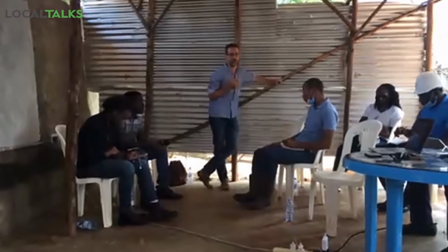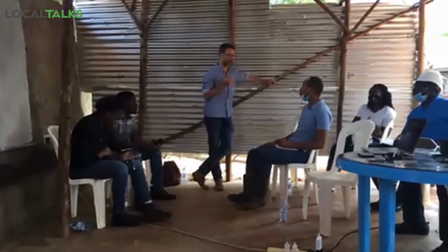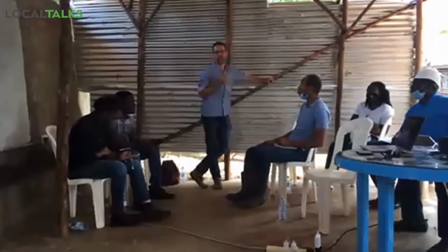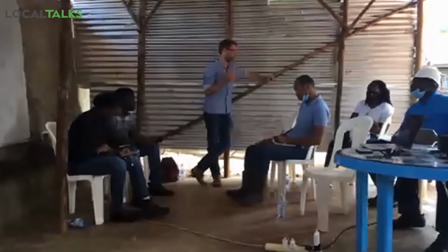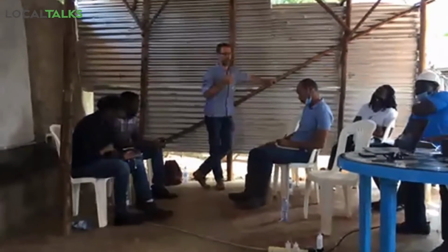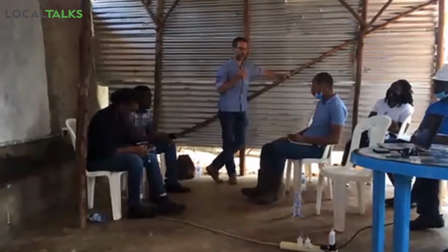And the rest is labor. And we have given you an indication of labor. We have roughly calculated that 4 guys can lay 54 bags in a day. And those are now the prime components that you could build up the cost with. The other calculation that we have done, which is more based on a square meter rate and based on a more global view on the construction, estimates the cost to be in the region of $15 per square meter.